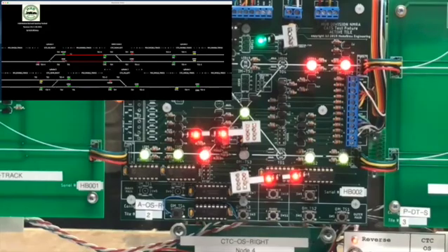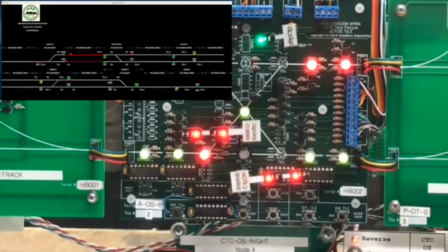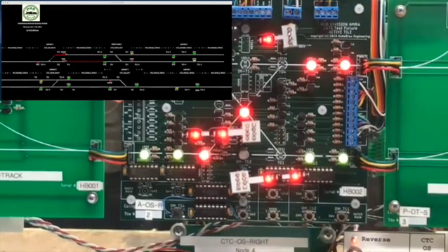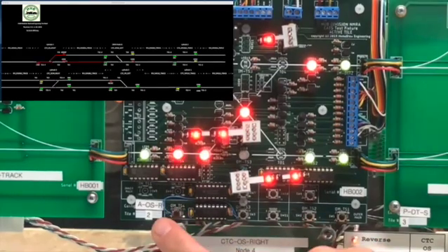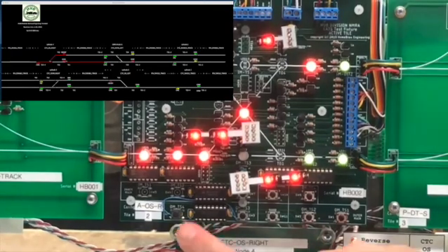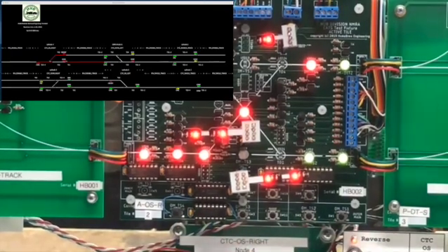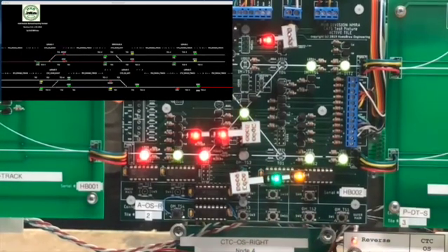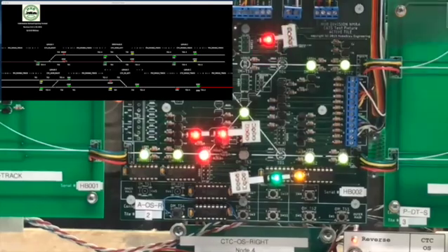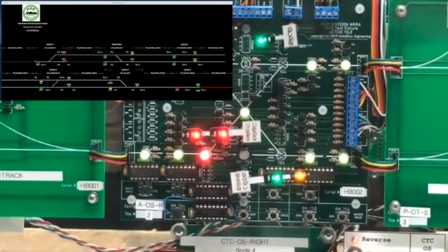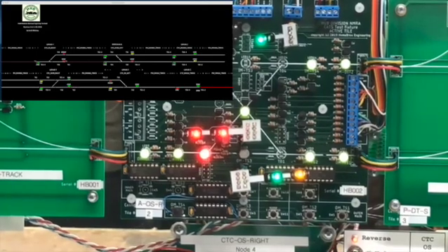With train 1 out of the way, the turnout is thrown and train 2 proceeds to the main. As with train 1, CATS follows the train movements as it goes from block to block to the left. You probably noticed that the blocks on the testbed are unrealistically short. This is because I wanted to be able to keep the testbed small enough to fit on a tabletop. It should be clear that in order to prevent CATS from getting confused, the train must be fully equipped with resistive wheel sets to make sure the block occupancy detectors don't clear in the middle of a train. This could confuse CATS into thinking there are more trains than there actually are. We can simulate this condition on the testbed by not pressing the right buttons.